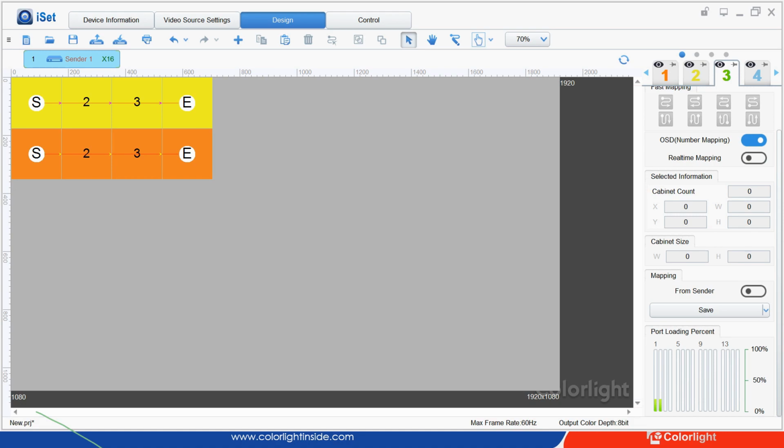So let's look back at the toolbar on the top of the software. Click the finger button to highlight your panel on the LED wall. You will be able to see a flashing box on the panel you highlighted. And if the panel has an indicator in the back, the indicator will flash differently than others. It could be flashing fast or changing color. This feature significantly helps field engineers do on-site troubleshooting.